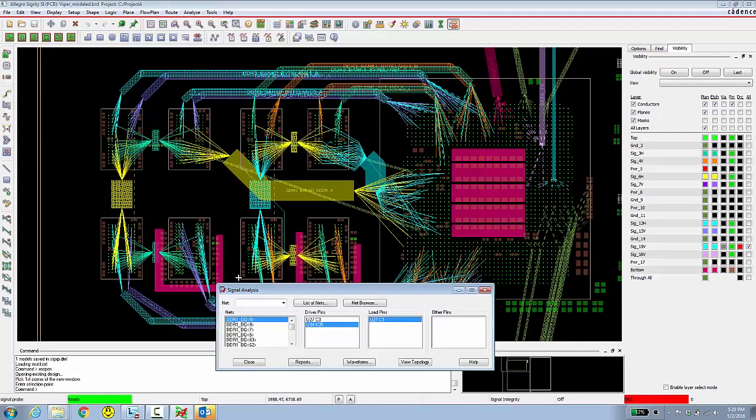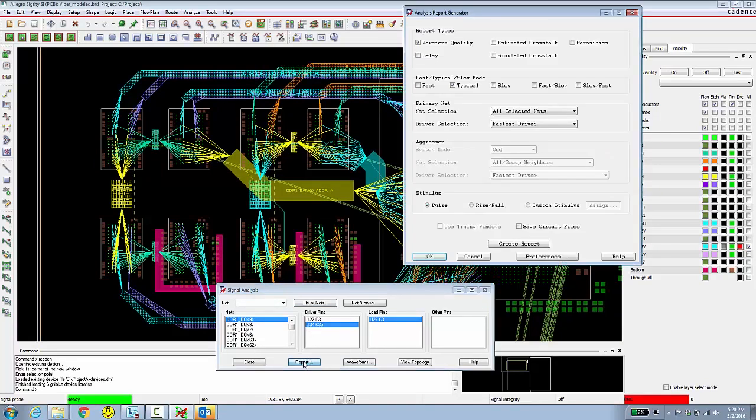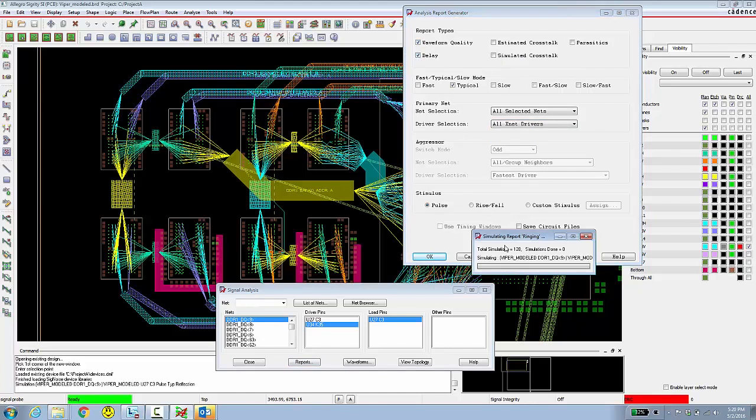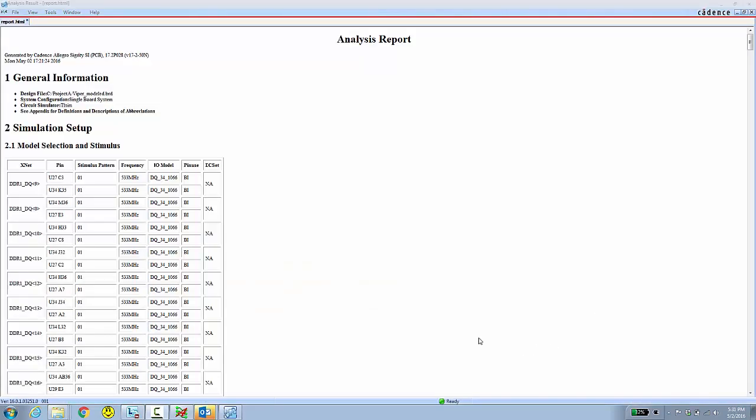If we wanted to take into account the difference in length for various nets without flow planning, it would be a tedious process to go alter the % Manhattan setting over and over for various groups of signals. This is no longer necessary now that flow planning is taken into account. If we run a simulation for the DQ nets in this interface, we can easily run all the nets in both directions and in very little time.